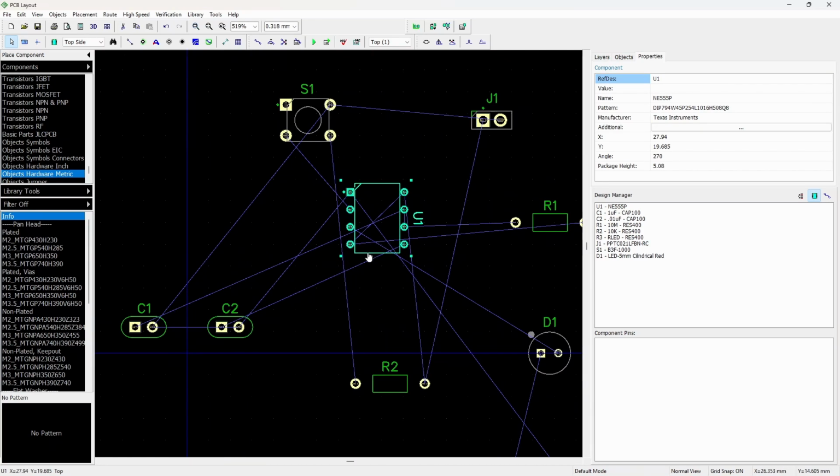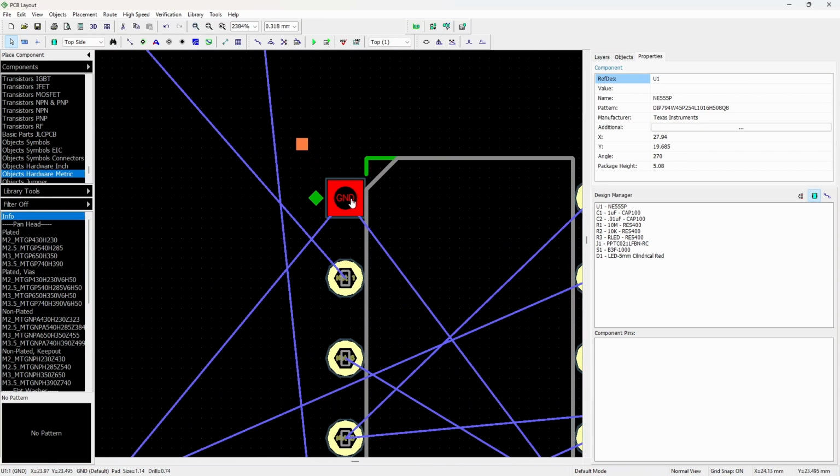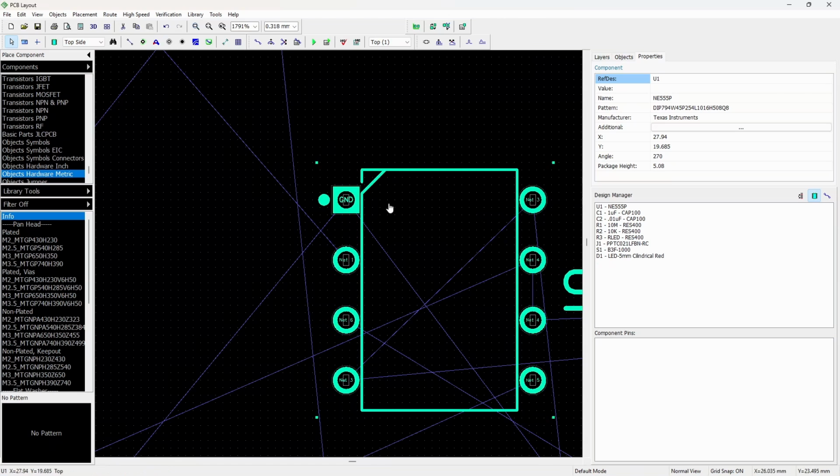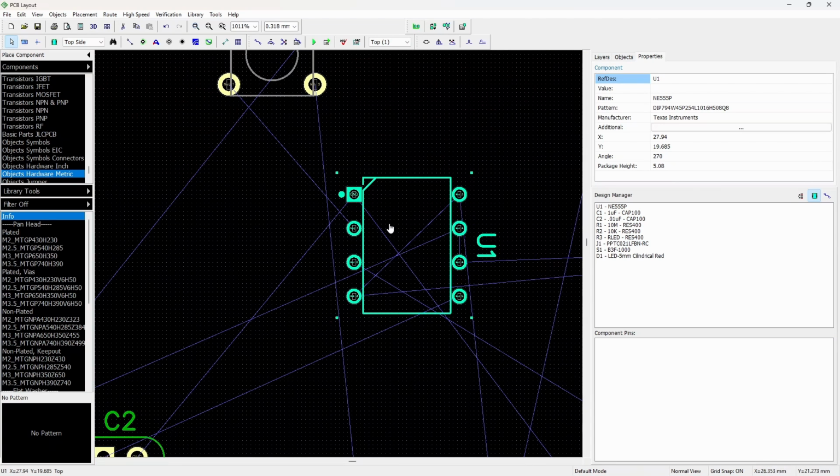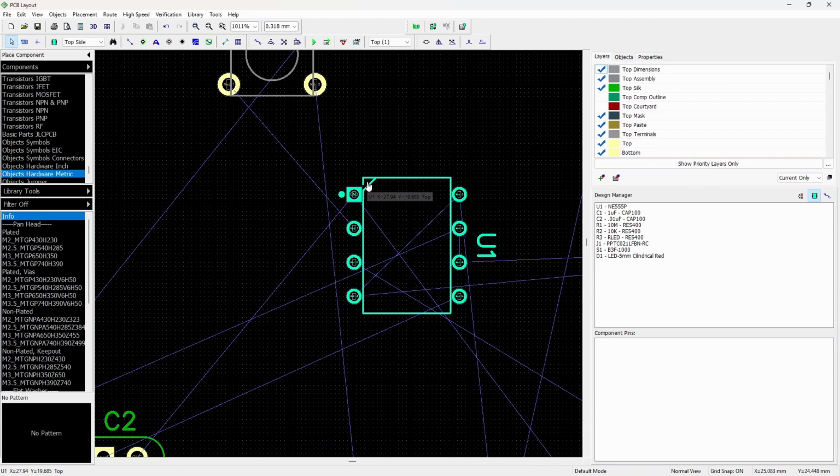So I'm just orienting this. If I zoom in, I can see where the different parts are, I mean, the different nets are. The only one I named was ground, and you can see this little notch is actually a screen print on the board, and that's showing where the pin 1 is. And also the square pad is another telltale sign.